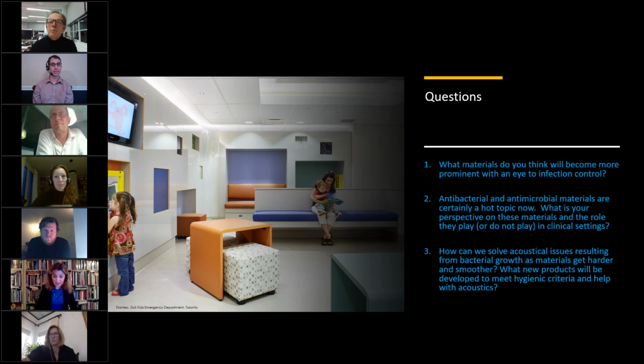Yeah, thank you. So just to quickly comment on the durability of materials, one thing that we've heard, which was kind of interesting, is that there's the regular cleaning procedure of the hospital, but then there's patient behaviors as well. A patient will come in, they'll sit down, they'll pull out their disinfecting wipe, and they'll start wiping everything down. So you also do need to plan that into your durable materials. And it's not going to be fun if you're throwing out your furniture every other year because it's falling apart because someone keeps taking an ethanol wipe to it.